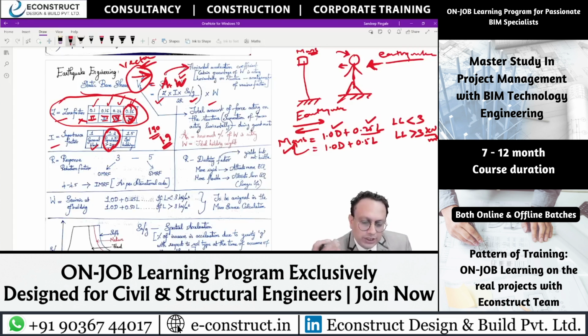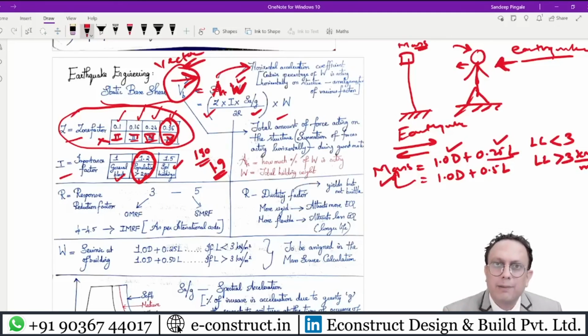Okay, that kind of importance we will be giving to that particular project. All right, 1.5. What is 1.5? These are special projects. What are the special projects? Let's say hospitals, metro projects, or administrative projects, which are very, very valuable and important projects, given utmost importance. Even if an earthquake comes, the economy should not get stagnant, and there shouldn't be heavy damage to society. That's why we give 1.5 as the importance factor to those projects.